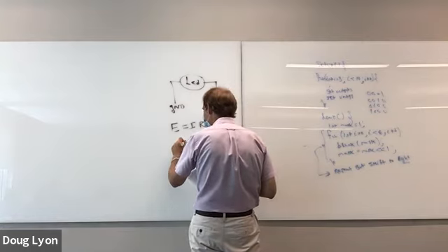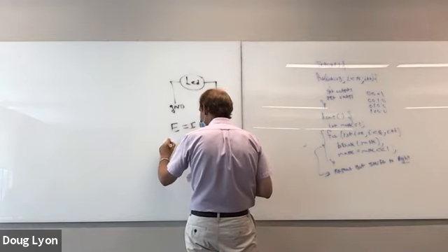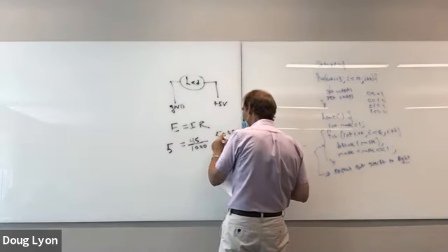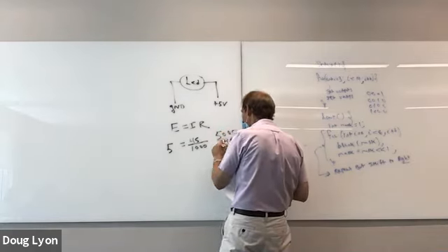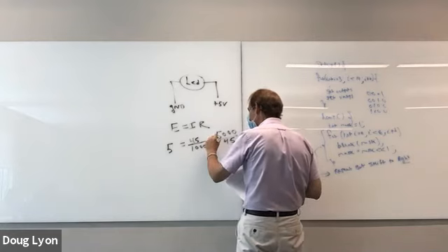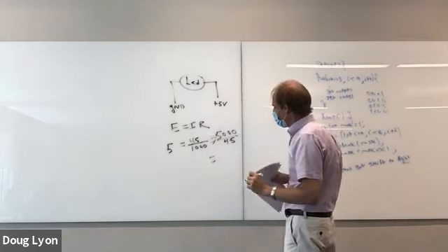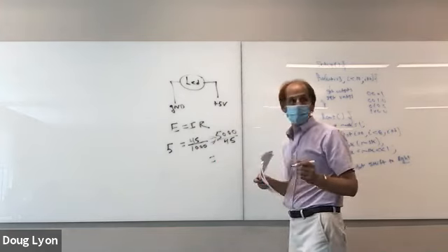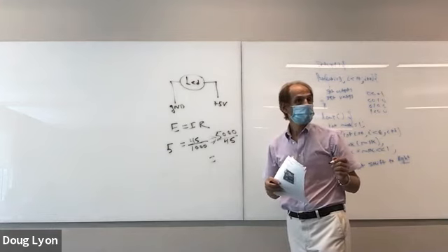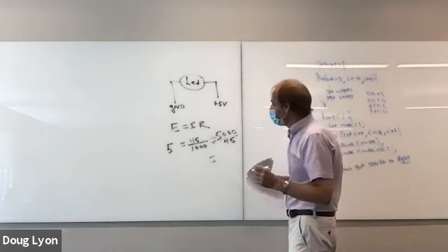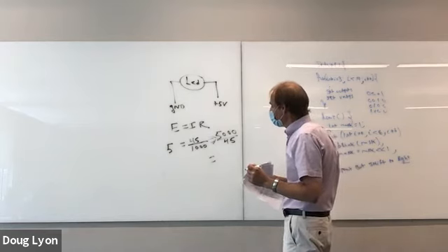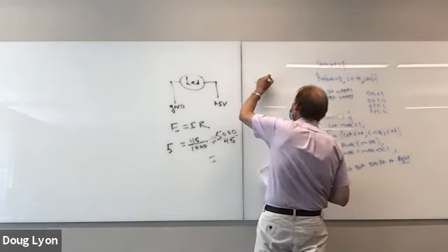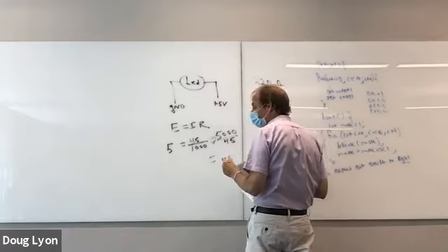And you might be tempted to do 5 volts in here, and then 5,000 over 45, and that might give you a resistance. If I did it divided by 50 milliamps, then I'd probably put in like 100 ohms. Yeah, it's like 111 ohms. Typically, what I see people use is something on the order of 220 ohms. I see people do that a lot. That's a very typical thing.